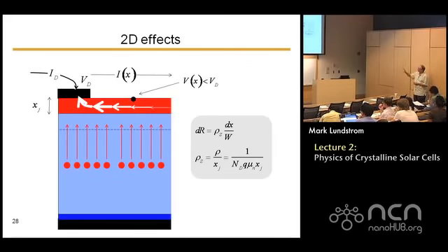So people will be very careful about trying to make sure that that layer is not too thin, because if it's too thin, its resistance is very high, and then these lateral voltage drops get very big. So when you're designing a grid, you'll be careful about the spacing between these metal fingers and about the sheet resistance of that top layer such that you don't introduce these lateral voltage drops.